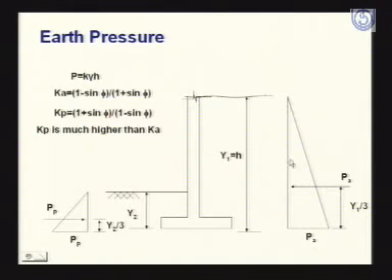This is the pressure variation of the earth pressure here, shown as a triangular variation. Here also on the other side, there is soil, earth is also on the other side. So here again the behavior of this earth pressure will be a triangular one, means linear variation, 0 at the top and maximum at the bottom. But you see here a difference between the two, because under the earth pressure this wall moves slightly, and ultimately the pressure coming on this wall is active earth pressure.